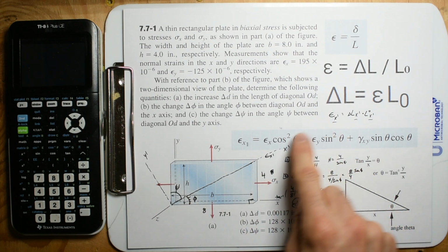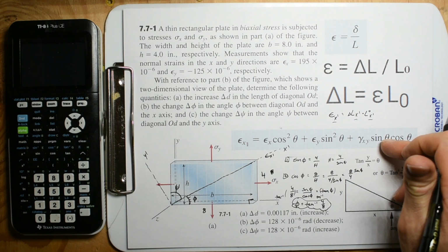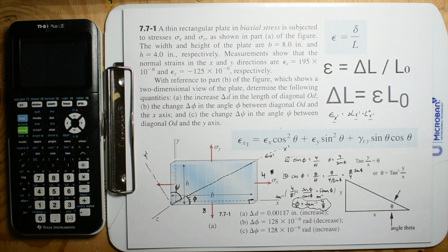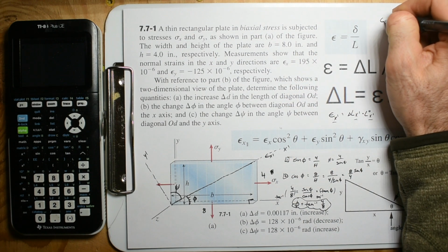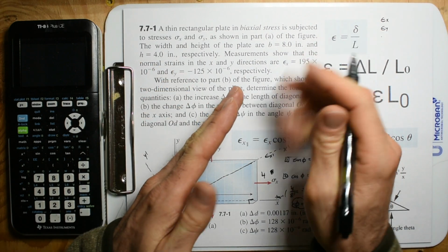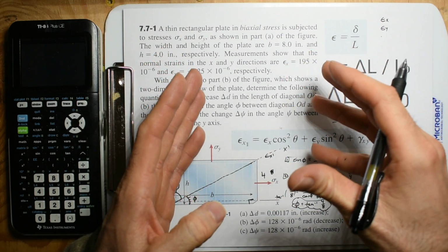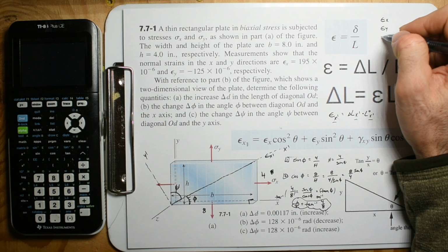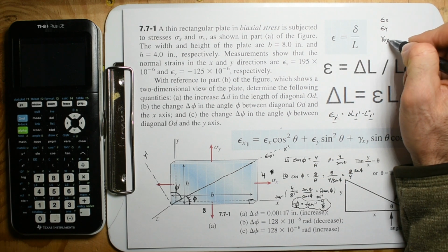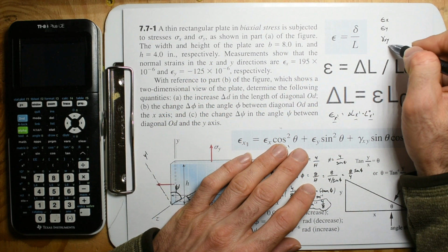The whole idea of this equation is that in all these problems, we know the strain in the x, the strain in the y, and the rotation, which is the angle that forms. Number-wise it can be similar or sometimes double, but it's going to be the strain in the xy. When we compare it with the Mohr circle, we actually divide this by 2.